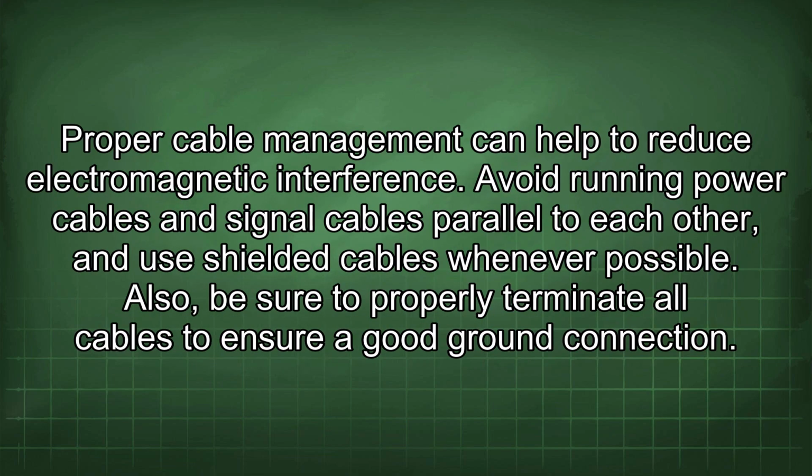Sixthly, consider cable management. Proper cable management can help to reduce electromagnetic interference. Avoid running power cables and signal cables parallel to each other, and use shielded cables whenever possible. Also, be sure to properly terminate all cables to ensure a good ground connection.